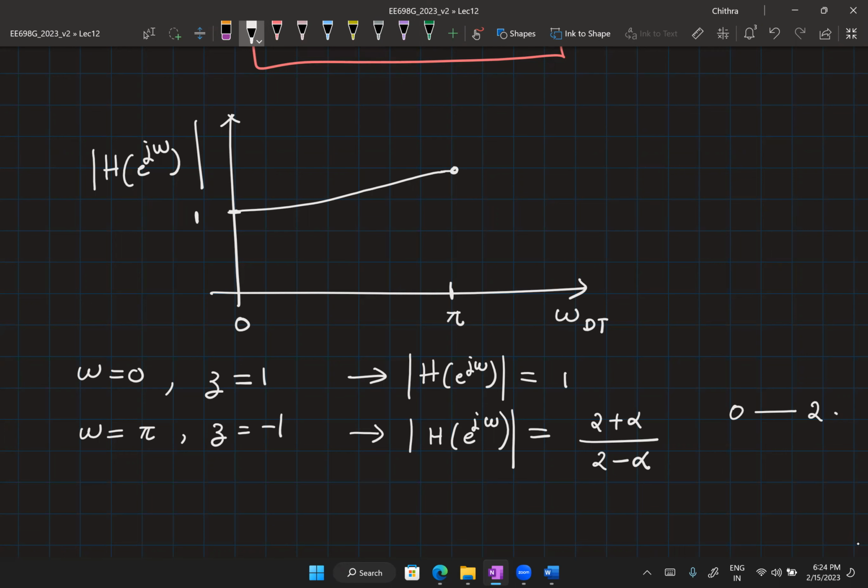And this is what we call jitter peaking, because if your input signal had a jitter, that jitter will be amplified by the DLL. Right? And if you want to suppress this jitter peaking, you can never make it 0 because alpha has to be greater than 0, right? So jitter peaking is always existent. And to make it minimal, you will have to reduce the value of omega u. So the time taken for the DLL to settle will increase if you want to minimize jitter peaking.